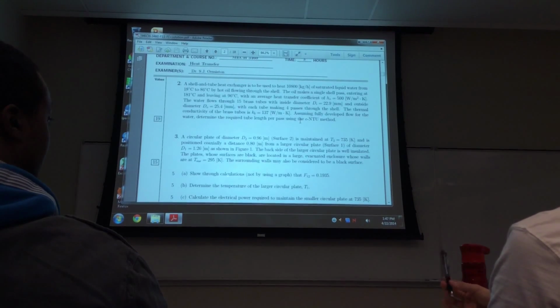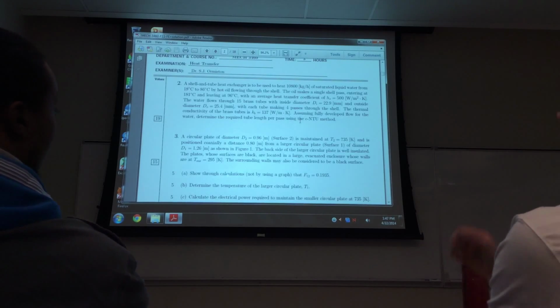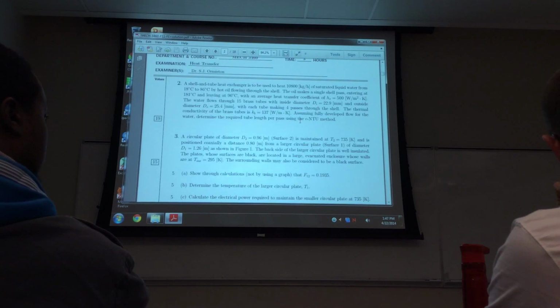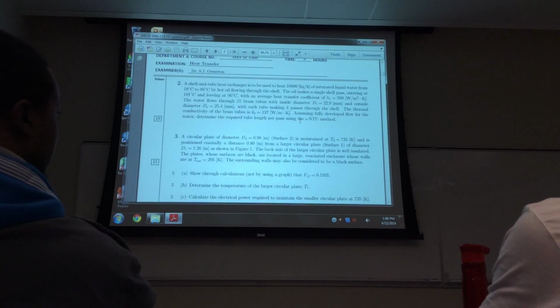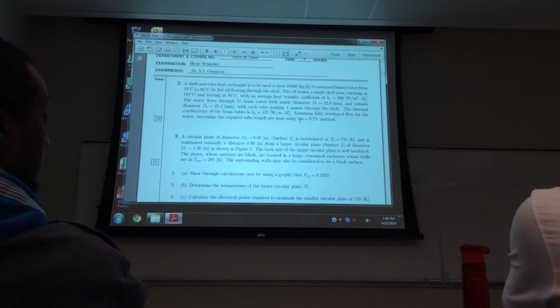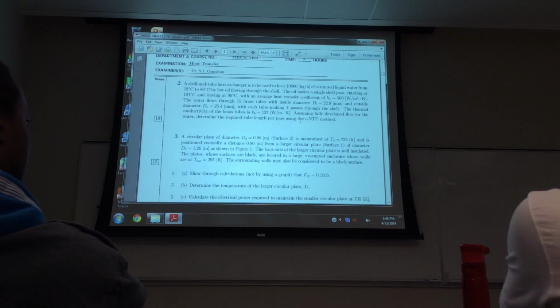What's the next suggestion? Well, the whole mixed versus unmixed thing, that's just based on turbulence and... Nope, no, the mixed versus unmixed: if you have tubes, the tube side is always unmixed, because it's in separate tubes. On the shell side, or the other side outside of the tubes, if it's an open tube bundle, it's mixed. If it has baffles or some kind of plates or passages that it goes in between, then that's unmixed.